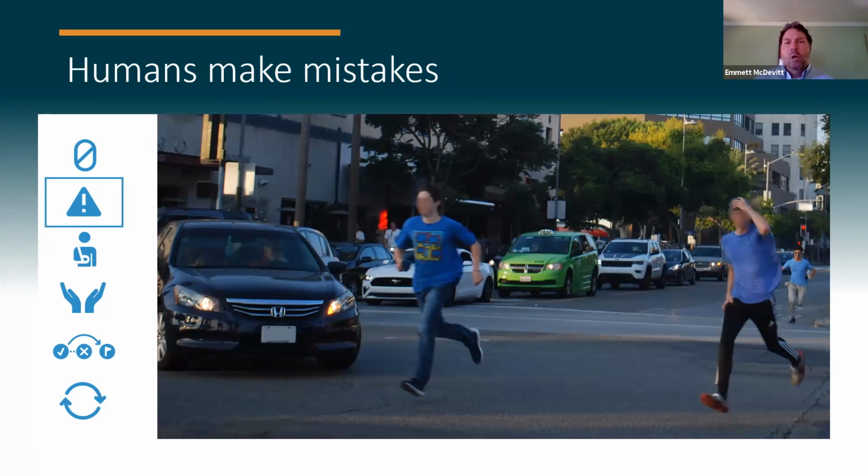As I mentioned, a pedestrian isn't going to go 350 or 400 feet to a very safe crossing. They're going to cross at mid-block. And one of the things that the safe systems approach does is recognize that they will make mistakes. They are going to text and drive. They are going to drink and drive. But the redundancy in the system accommodates those mistakes.